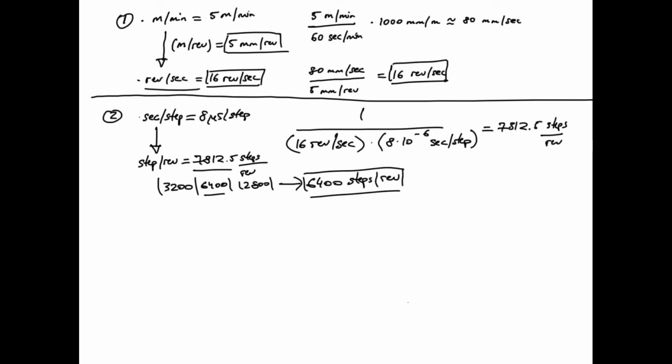Okay, and now we have to use, in step number 3, some sort of a revolutions per second value, and the updated stepper driver steps per revolution value. We have to calculate from that an actual seconds per step value of the motor. And this actual seconds per step value will always be equal or higher than the minimum allowable seconds per step value of the motor, due to us selecting this lower or equal value of steps per revolution in previous steps. So this one right here.